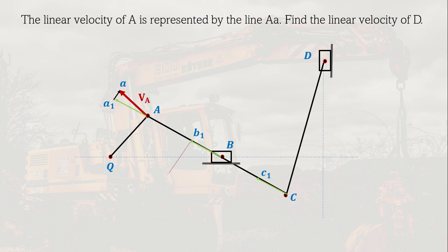So this is the arrow that is perpendicular to the head of BB1. So as you can see here, BB1, and then we have an arrow. So therefore, we can get the velocity of B, obviously, by connecting the tail to the head of the last vector or the last arrow. So this is the direction, therefore, of point B. So this is B, B, and this is our absolute velocity of point B.